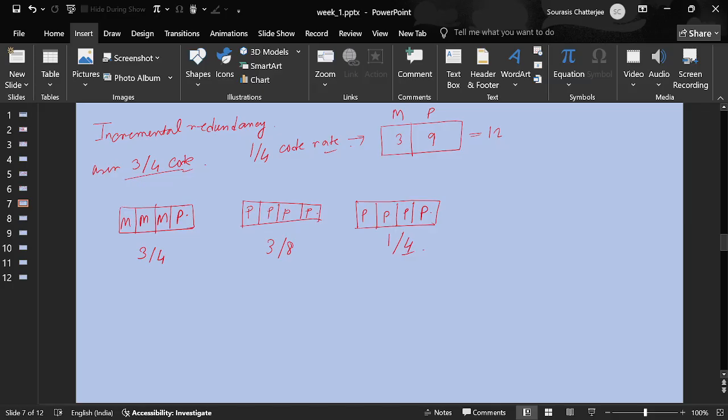I think it depends on the SNR. Okay, it does depend on the SNR, true. For example, what I mean by bad transmission is that you are not able to get almost any message bits at all. So what is the issue there? Low SNR. Actually in that case, in incremental redundancy, the systematic bits are only in the first transmission. So if you are not able to decode the message bits, then there is no use of these parity bits. Correct, correct. If the initial transmission is so poor, then the additional parity bits won't help you much.